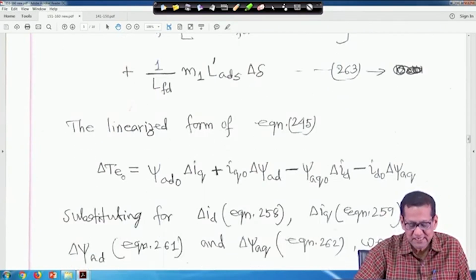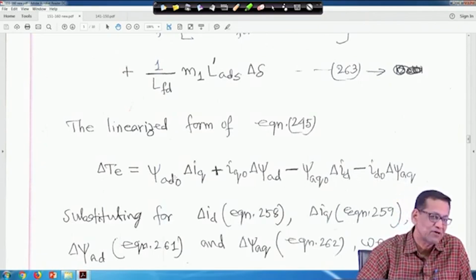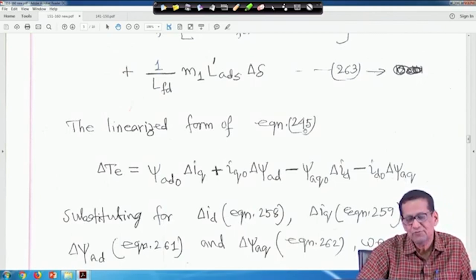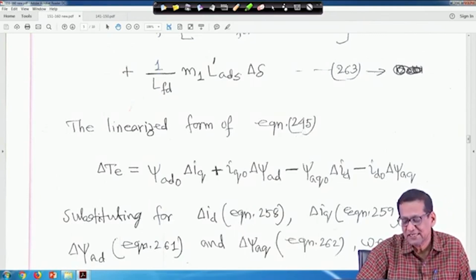So, you will get delta T is equal to psi d0 delta I q plus I q0 delta psi a d minus psi a q0 delta I d minus I d0 delta psi a q, just you take the small perturbation in equation 245. I am not going to the expression again, but when you listen to this video, just keep those equations and try yourself once, only once.